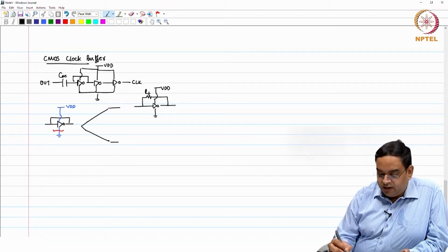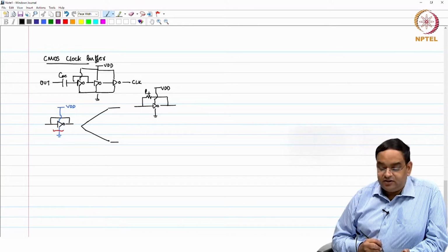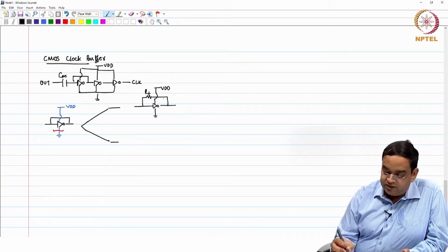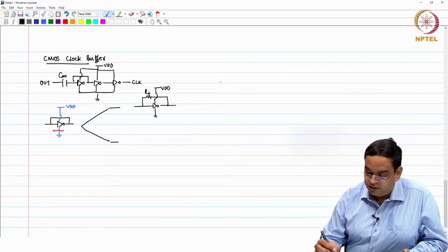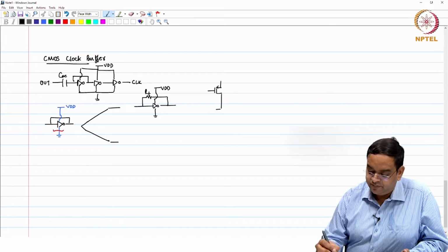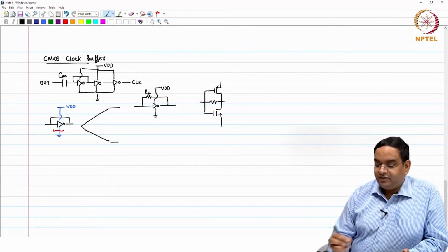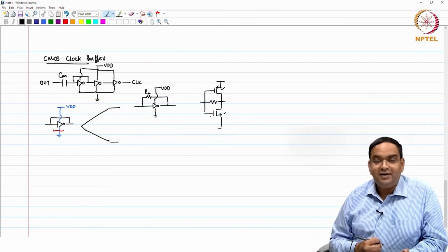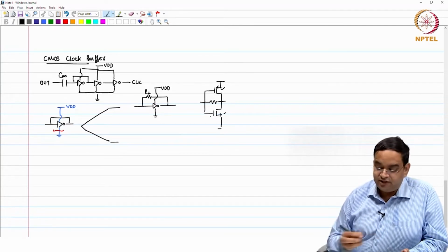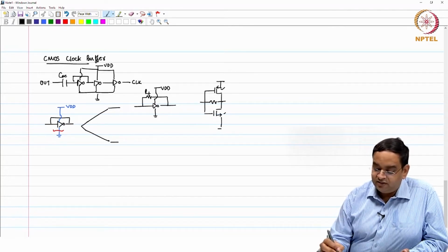So, when you connect a resistor in feedback across the inverter, between input and output, this inverter is going to be biased for sure like this. So, PMOS and NMOS are still conducting current always, and they are biased in saturation. Your DC operating point is such that the potentials Vin and Vout are both the same.